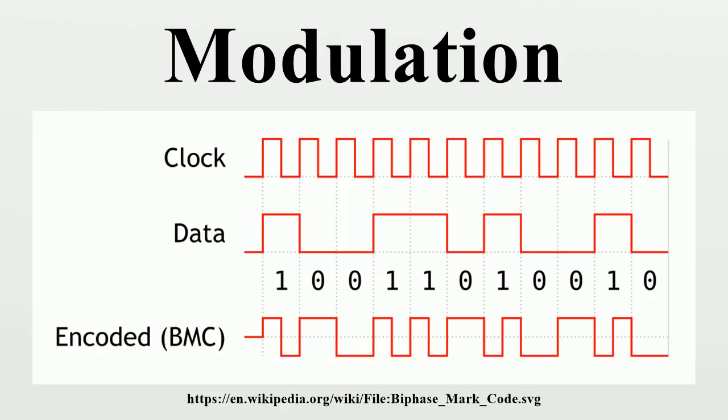OFDM is based on the idea of frequency division multiplexing, but the multiplex streams are all parts of a single original stream. The bit stream is split into several parallel data streams, each transferred over its own subcarrier using some conventional digital modulation scheme. The modulated subcarriers are summed to form an OFDM signal. This dividing and recombining helps with handling channel impairments.